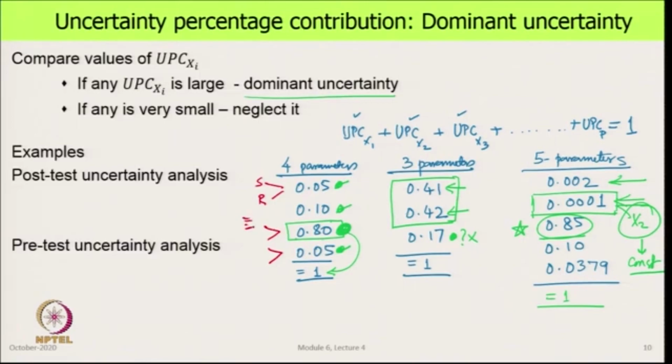And you will find that there are some random causes and there are some systematic causes. Then by comparing those, you can figure out which one is the main culprit that is making a big contribution here. And again, like the others, you will find one or two or three of these which are large contributors to the total uncertainty of that measurement. Then we can say, now that is where I need to focus.